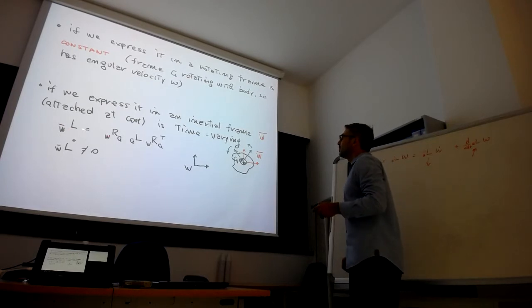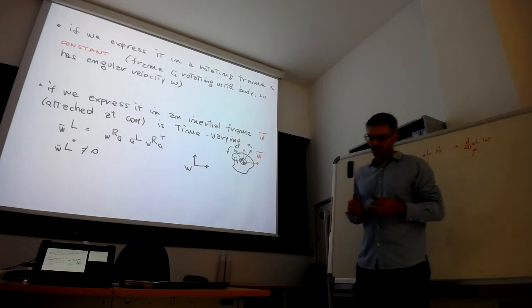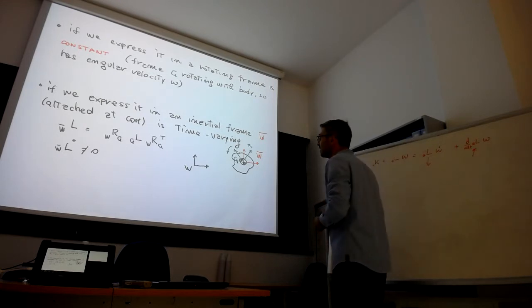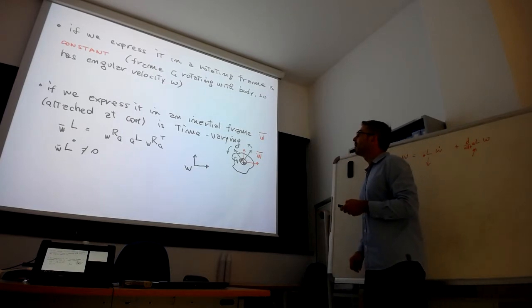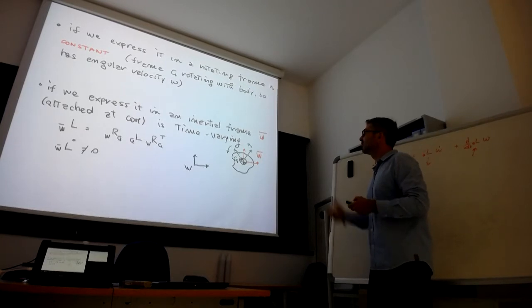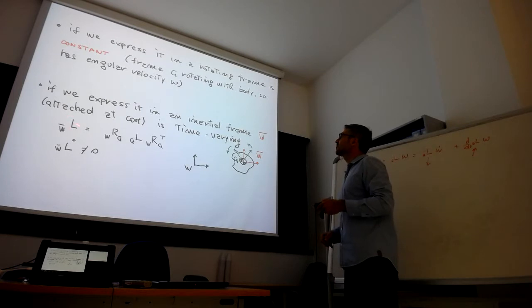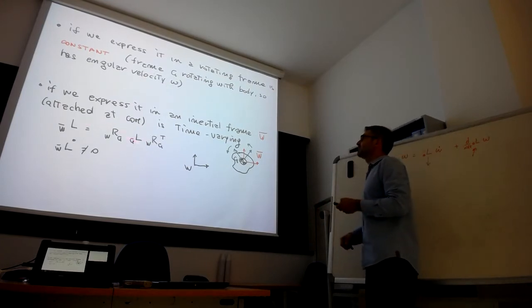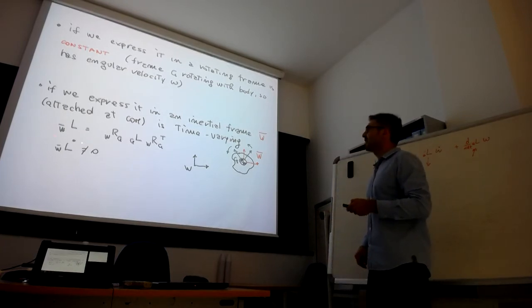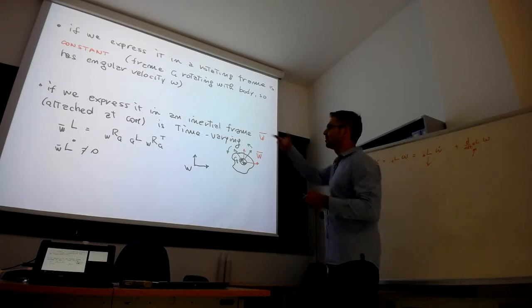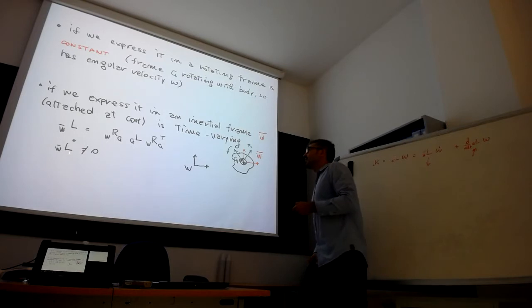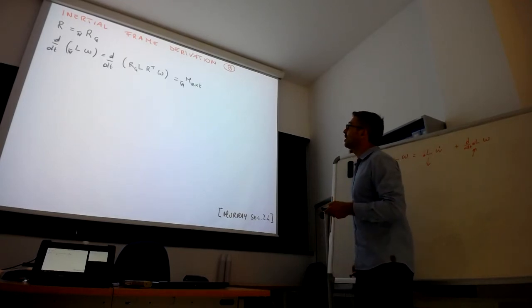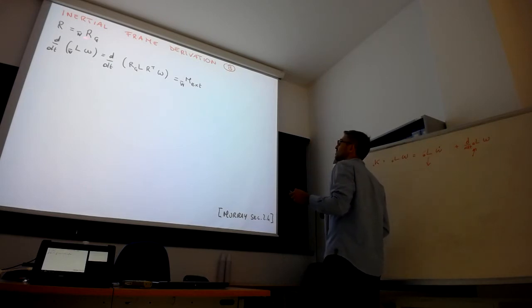So in this case, from our CAD software, where we model our robot in 3D, we can compute the value of the tensor of inertia in the center of mass frame, aligned with the body. To compute the tensor of inertia in the frame W bar, we need to pre and post multiply by the rotation matrix that maps the frame G into W bar. And this means that since the rotation matrix is time varying with the orientation of the body, then the derivative with respect to time of this tensor of inertia will not be zero. It will not be constant. The tensor of inertia is no longer constant. So to simplify the notation, we just call this matrix R.